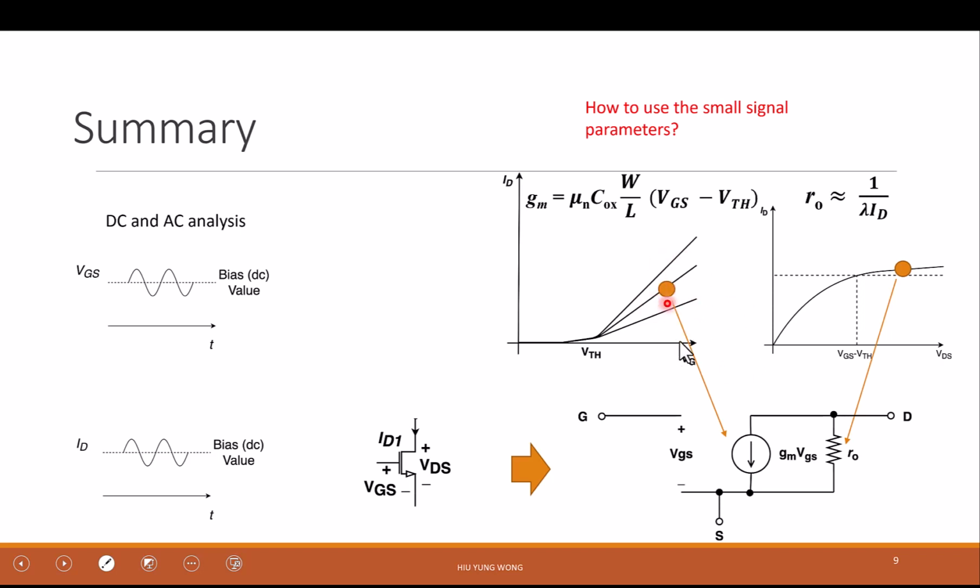So we have this curve. This transistor is very complicated, but its characteristic can be represented by this curve. We bias it at a certain VGS, certain VDS. Then we will only care about the slope at that point. And from there, we will build a small signal model. So this complicated transistor now becomes, although you think it's more complicated, actually simpler. It has two more elements, that is true, but they're all linear.